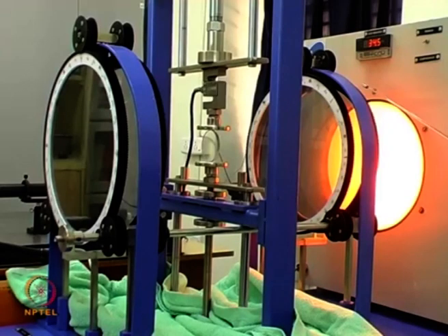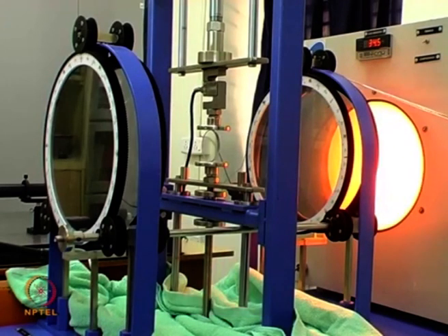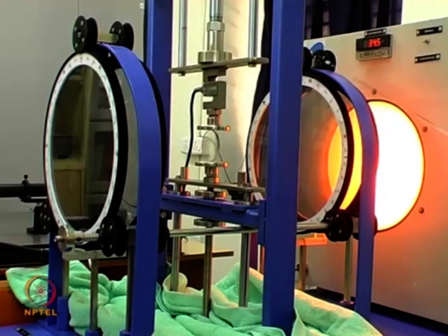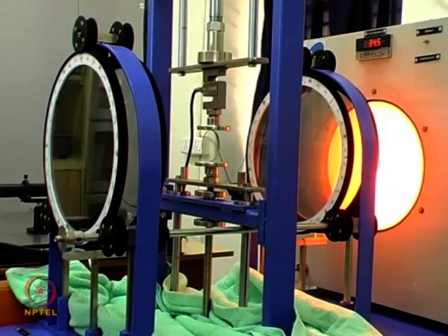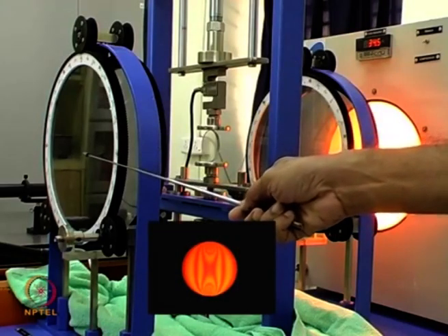See, the basic optical arrangement of the polariscope is in dark field. So, what we will have is polarizer, analyzer are crossed, first quarter wave plate and second quarter wave plate are crossed. When you have both the pairs crossed, you will essentially see a dark field.